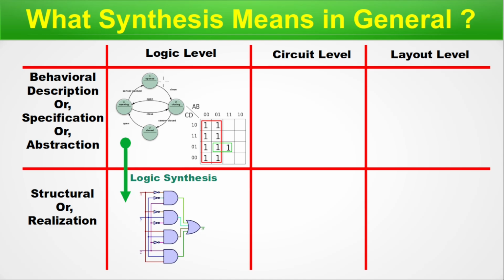And when you do the logic synthesis, this conversion process, you get the structural part in terms of logic circuits where the gates are pre-existing in the standard cells. That means your synthesis tool is well connected to your standard cell library, from where it picks up the standard cells and places them as per your design. This is also a part of EDA, that is electronic design automation. So now you understand that you are at the first step of the VLSI design.